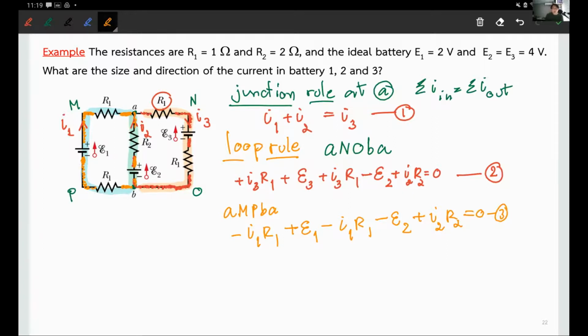Okay? All right, cool. So I think that's clear up what Kirchoff's rule is and how to apply junction rule and loops rule. Actually, it's a rule that I think you guys already agree. Junction is just current in equal to current out. Loop rule is just every time you come back to the original position, whatever potential difference that you have gone through must sum up to 0. Okay. All right, that's the correct expression for it.